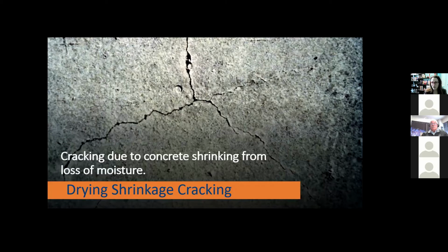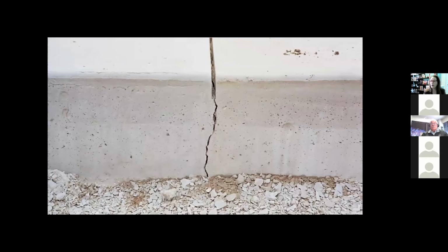If you end up with a straight crack, that just means that somehow it had a relief plane. Maybe the stress buildup was really more settlement cracking because of reinforcing steel underneath. But what we also get for drying shrinkage cracks, when you're doing things correctly, if you tell concrete where to crack, it will dry shrink in the joint and activate that joint.